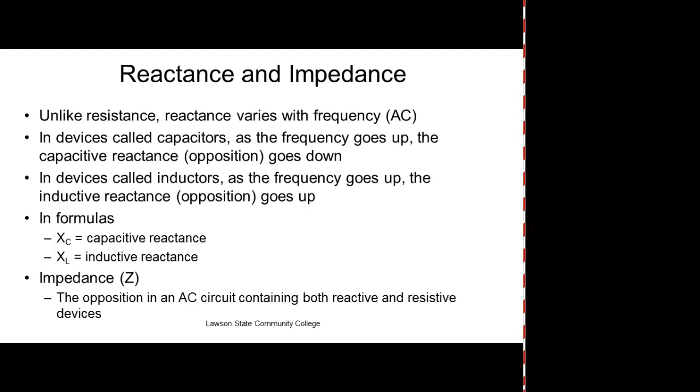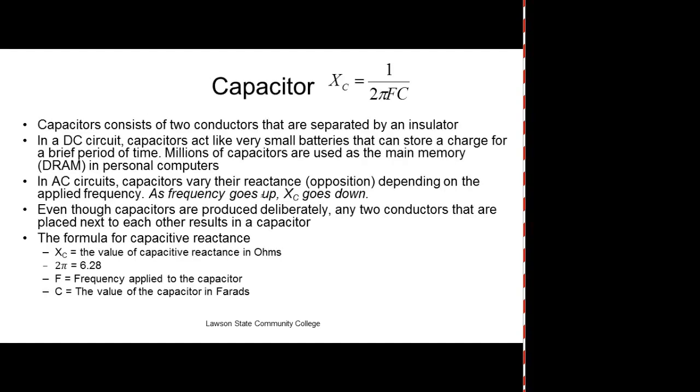The first power supplies we're going to look at are what we call unfiltered power supplies. And we'll see exactly what we get out of these things we call rectifiers. And then we're going to slap a capacitor on there, and you can see now we have DC. So rectifiers produce a type of DC we call pulsating DC. We'll see that. We can see it now because we've got these oscilloscopes, which is really, really neat. So capacitors do a lot of neat stuff. And here are the formulas, but you don't need to know the formulas here. All you've got to know is some general rules.